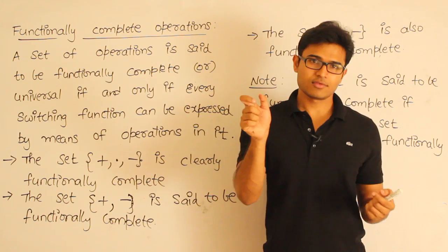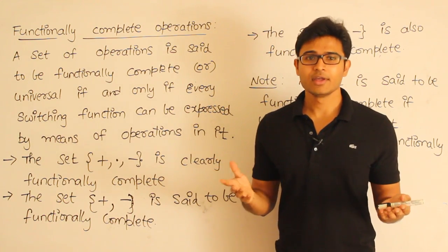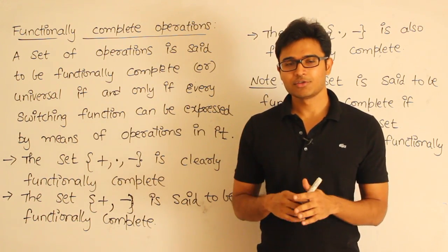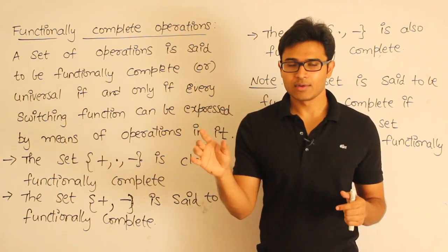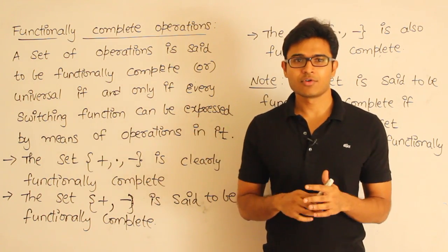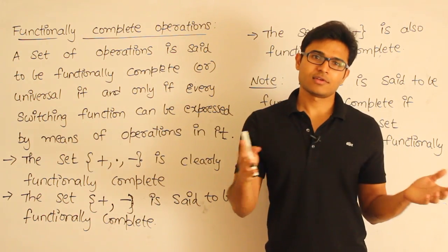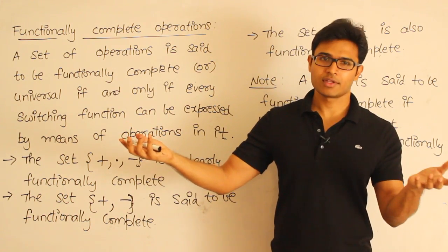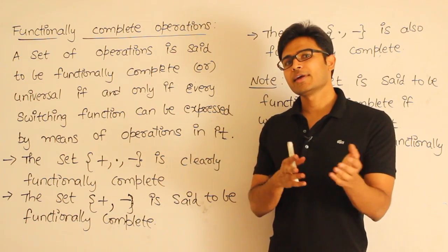Right? So it is always better if you could come up with only one circuit which is functionally complete, and that is what people are doing now. That is NAND and NOR. These two are functionally complete. Using only NAND you can implement anything. Using only NOR you can implement anything. Therefore let the company manufacture lots of NANDs, and if a customer wants one, they will always buy only one gate. Therefore there is nothing called leftover, because you can again sell them.